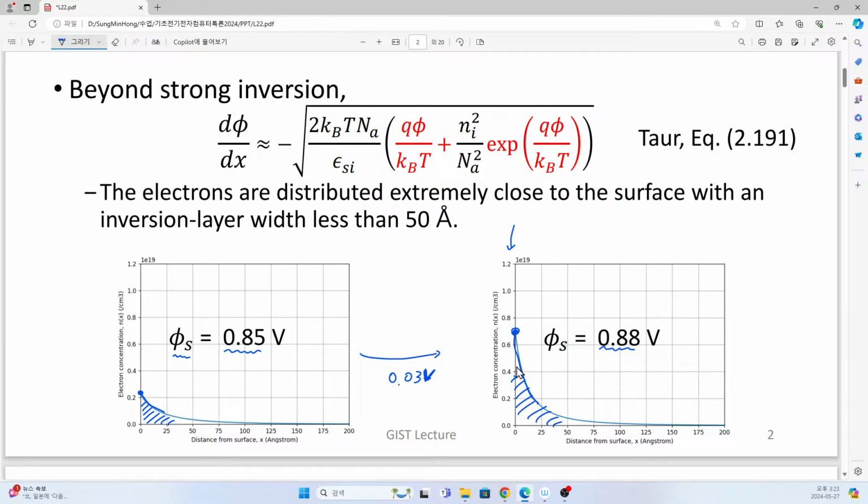However, at the end of our previous lecture, I told you that actually we have a slight distance from this exact point. In this case we have silicon, and this is silicon dioxide, and from the viewpoint of electrons in the silicon, this silicon dioxide is regarded as a very high barrier.